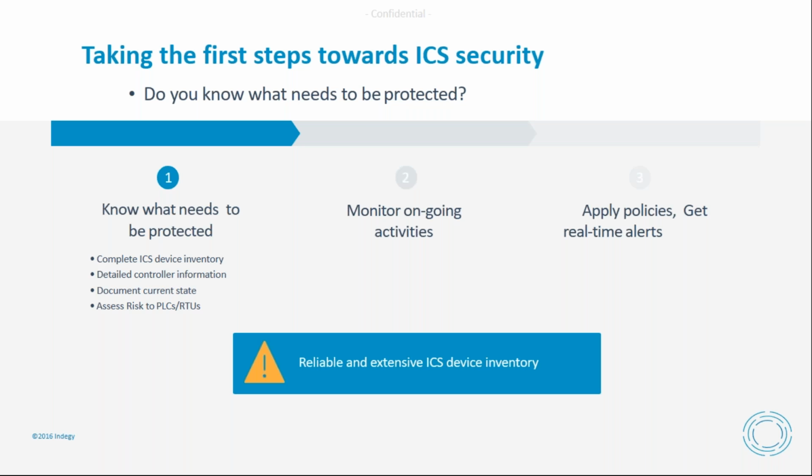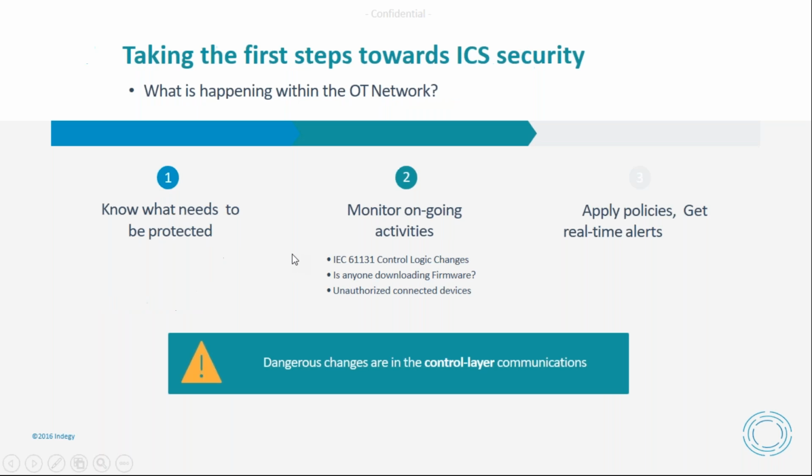If you have other vendors that don't have those type tools, you might be going out to panels and walking it down to figure out what you have where, and you might miss stuff. So you need a good way to figure out what you have and what vintage it is, what firmware is loaded, what the part numbers are. So you need a comprehensive asset inventory.